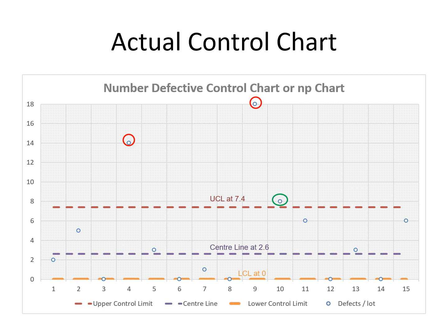Just imagine had we used the fraction defective chart, the numbers would have been way too small because everything would have got divided by 400. So it would have been 0.00 something, which would not have been feasible. Similarly, if you remember the first problem that we discussed in the case of fraction defective chart, the number of defectives was in a few hundreds, ranging from 200 to something. So again, that would have been cumbersome had we used the number defective chart. So yes, both the charts can be used in either case, but we use the chart accordingly so that the value we get is more meaningful and easy to handle.